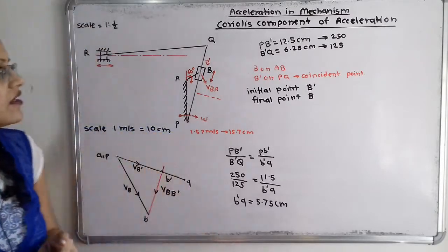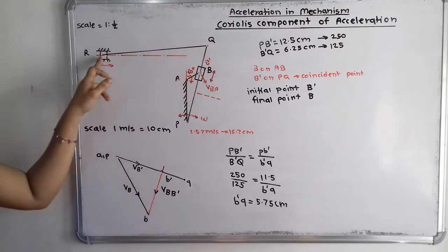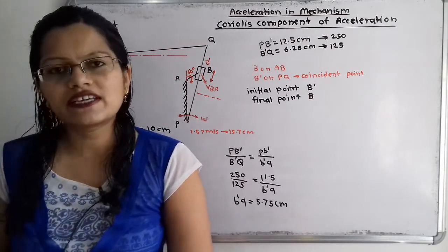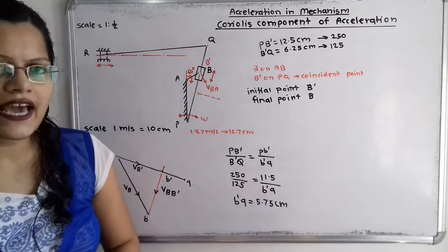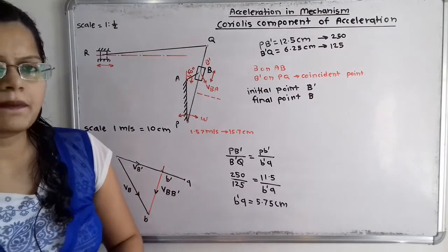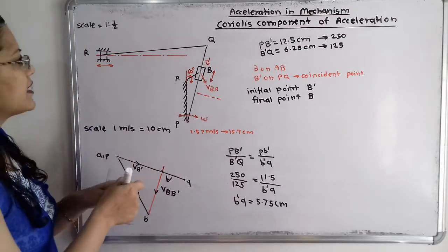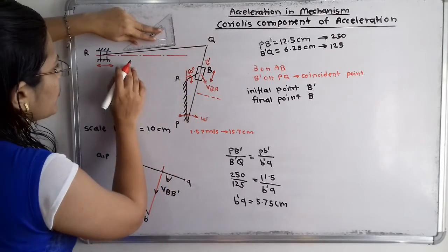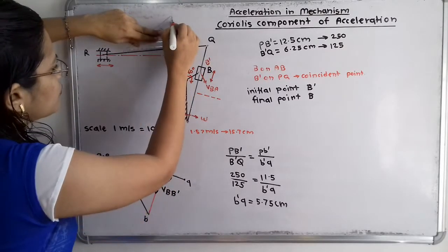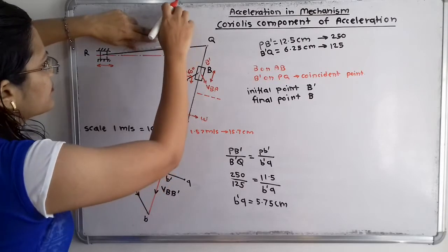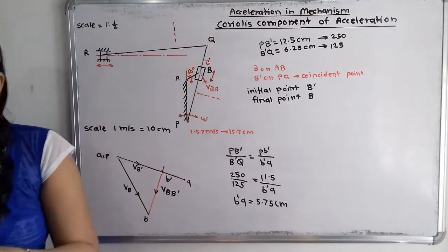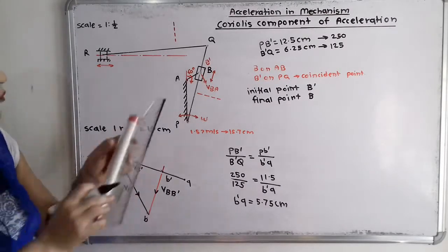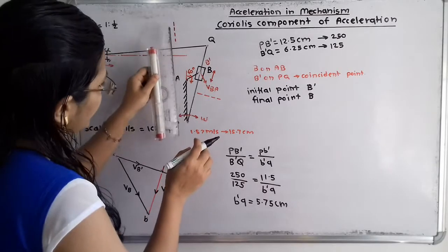Now if we observe, this point Q is attached with this link QR. So again we will draw the velocity for this link QR. It is in the perpendicular direction. So I will take here one perpendicular line to this link QR. So I will align one edge with this link QR, and from the other edge I will draw here one perpendicular line. So now take the line parallel to this construction line passing through the point Q.